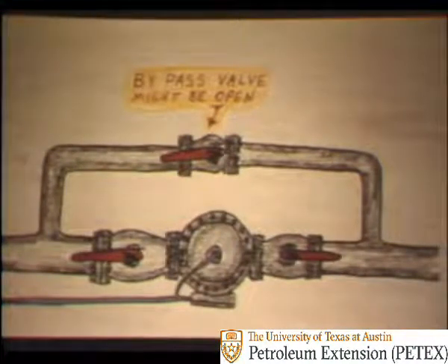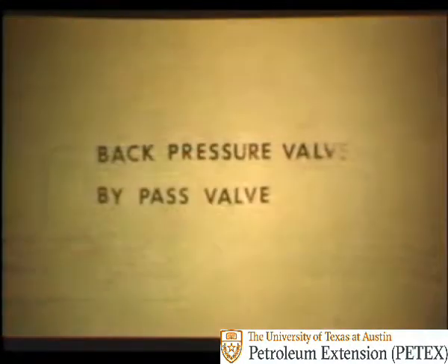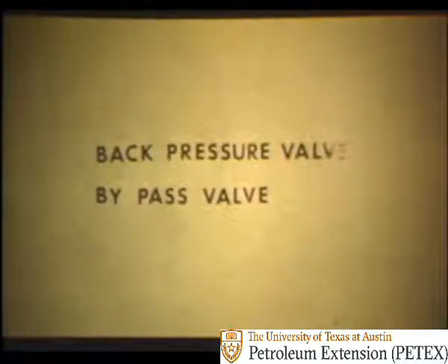Or the bypass valve around the back pressure valve might have been left in the open position, allowing the pressure to drop, even with the back pressure valve functioning properly. So if you're confronted with the problem, check the back pressure valve to see if it's hung open, or perhaps the trim cut out, and check the back pressure valve bypass valve to see if it might be open.